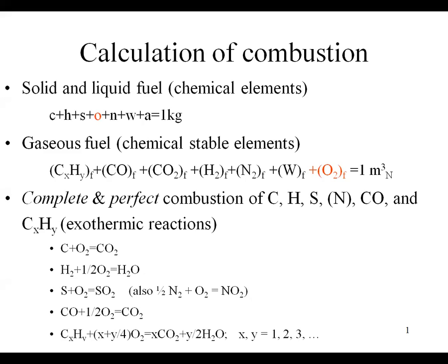So we are going back to our calculation of combustion. So you don't have to think when you see the word combustion that you are doing combustion of coal or oil or gas. The combustion can occur with all materials containing chemical elements that are easy to go into an exothermal reaction with oxygen. And these elements are carbon, hydrogen, sulfur, also nitrogen, hydrocarbons, and so on.